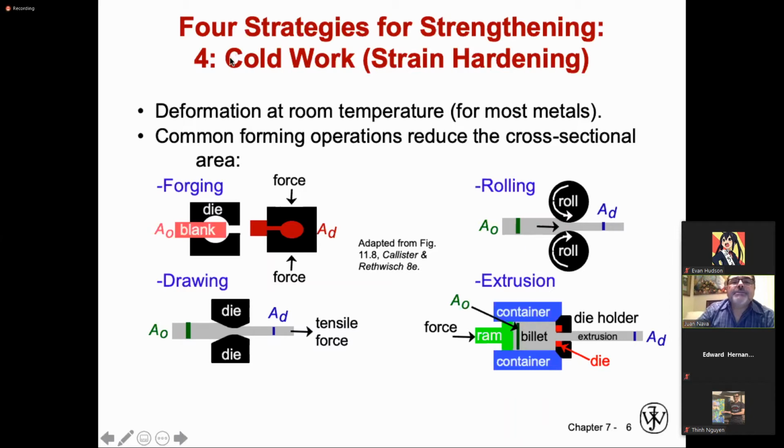And that process is normally referred to as cold work, because you can achieve this with the majority of the alloys that are amenable to straining. Remember, when we draw the true stress, true strain diagram, you will be able to calculate the strain hardening parameter M, so you will be able to make an assessment of how amenable to deformation or strengthening by plastic deformation that material will be.